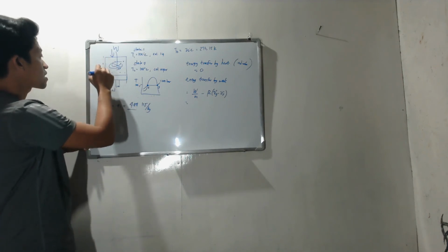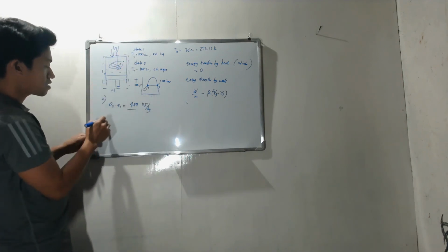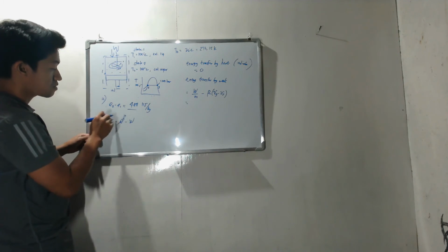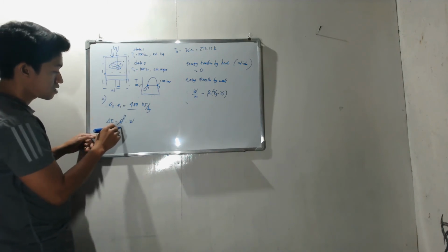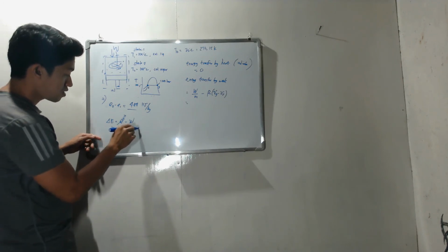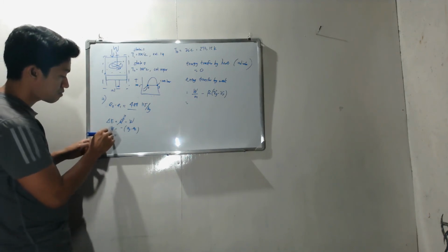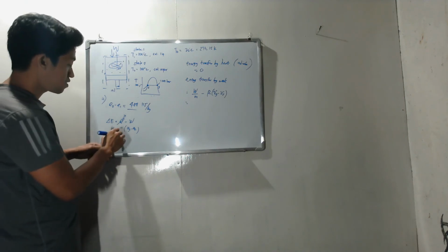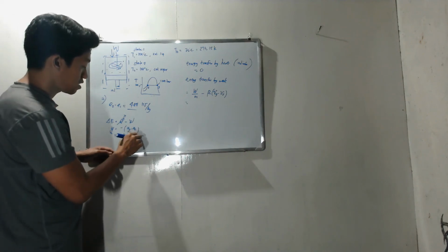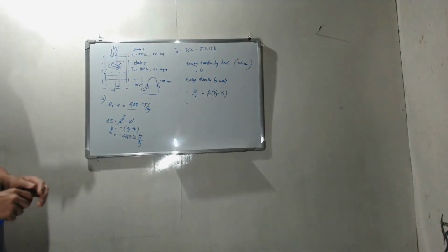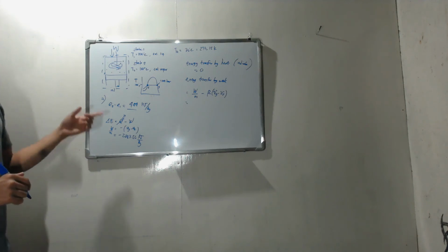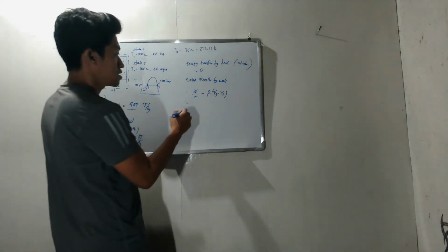Apply the first law, Q minus W. Q is 0, so the work is just negative of (Ug minus Uf), or work over m is just negative 0.56. Negative because it goes into the system.